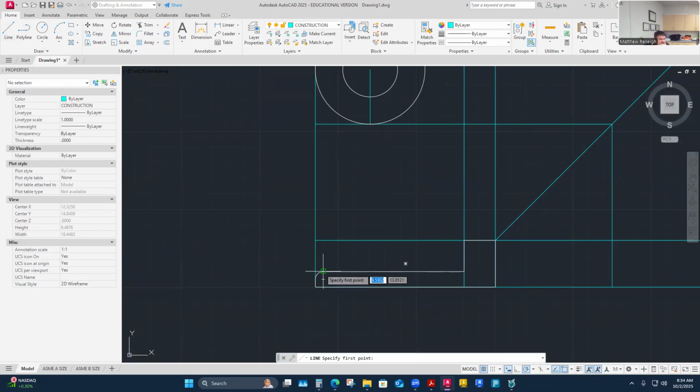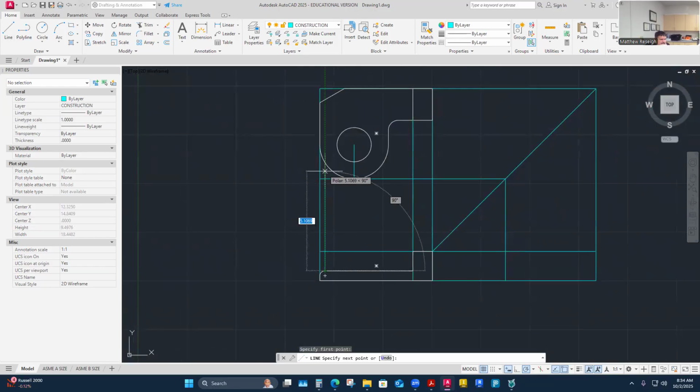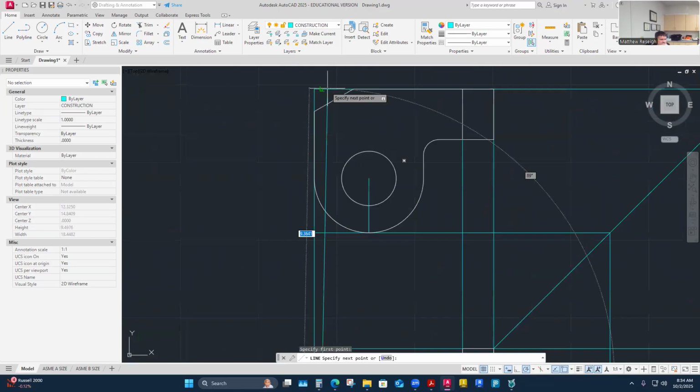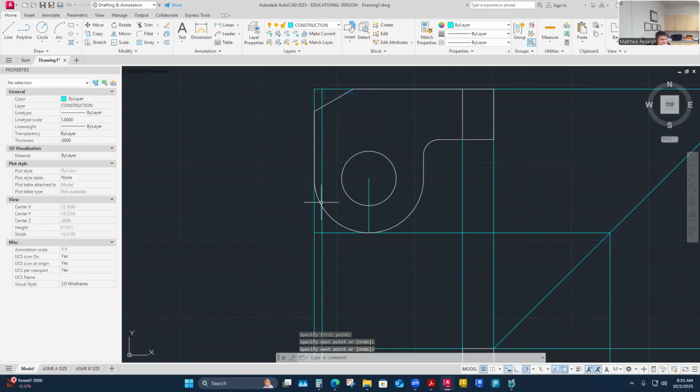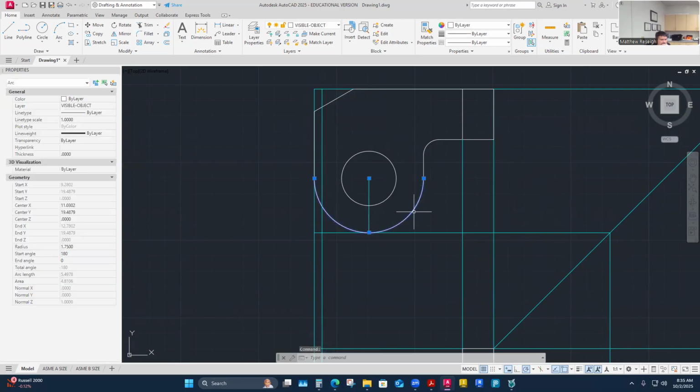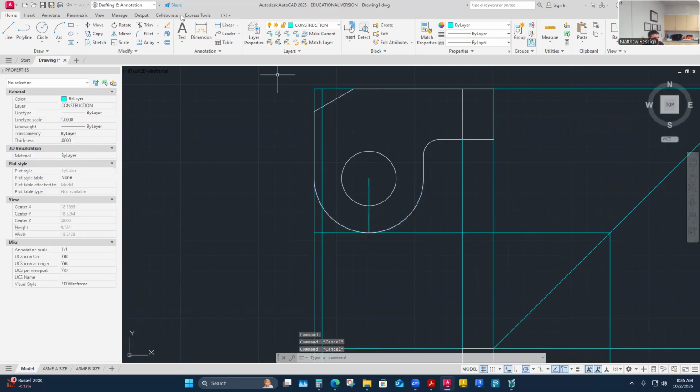And I can project that little radius up. So I'm still kind of working back and forth between my top and front, but this radius, I'll just pull it clear across. Really, it only needs to go there, but this is going to be kind of a hard line right here, but it's going to meet where I see the fillet here. So I think I can offset this to show that that's radiused on that edge. Offset this particular part, a 1/4 inch offset.